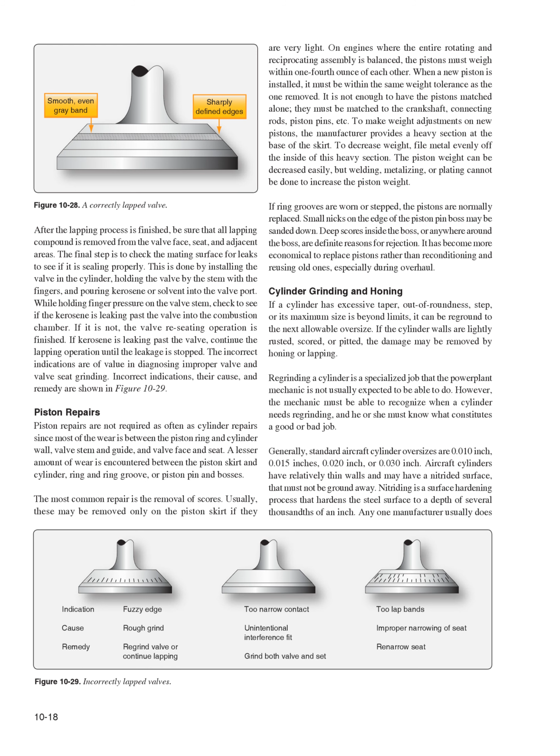If ring grooves are worn or stepped, the pistons are normally replaced. Small nicks on the edge of the piston pin boss may be sanded down. Deep scores inside the boss, or anywhere around the boss, are definite reasons for rejection. It has become more economical to replace pistons rather than reconditioning and reusing old ones, especially during overhaul. Cylinder grinding and honing.